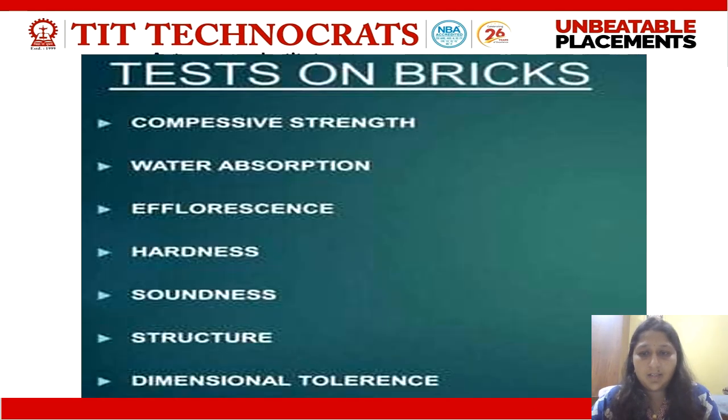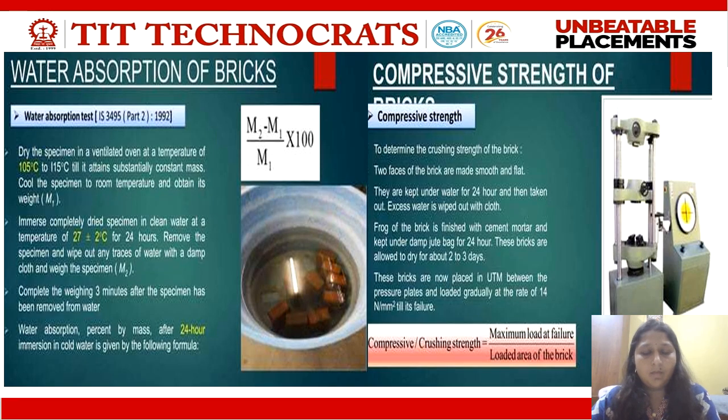The few tests conducted on bricks are compressive strength, water absorption test, efflorescence test, hardness test, soundness test, structure and dimensional tolerance. Let us discuss the very first and simplest test, the water absorption test.